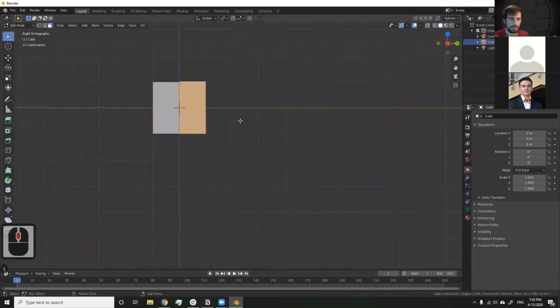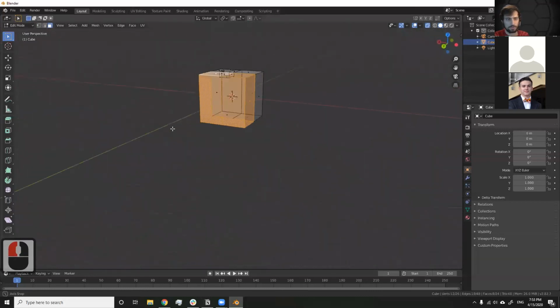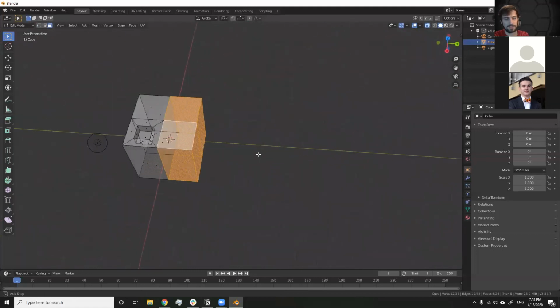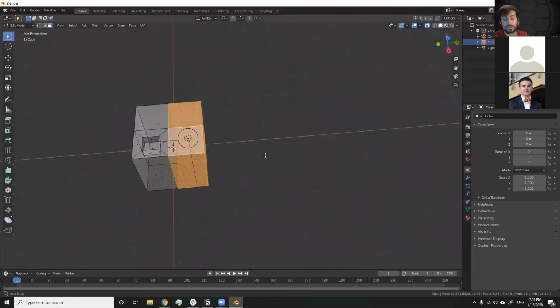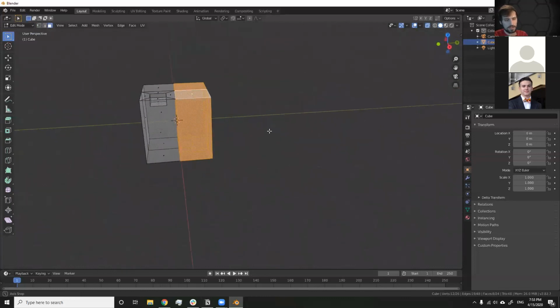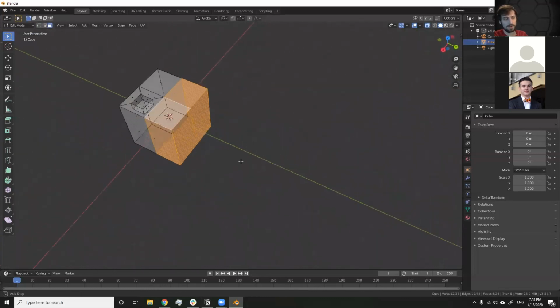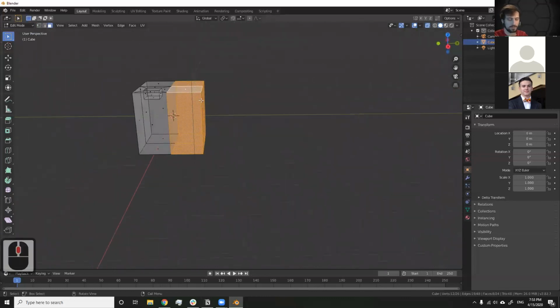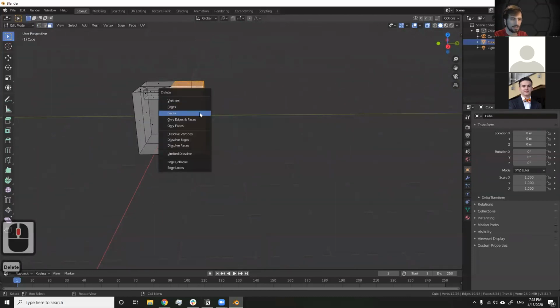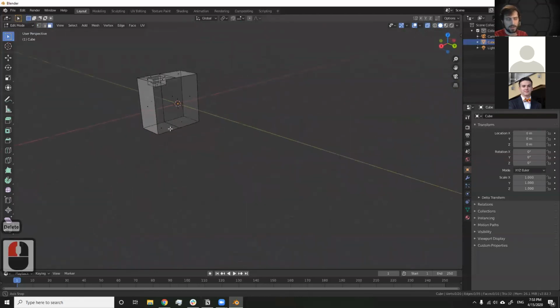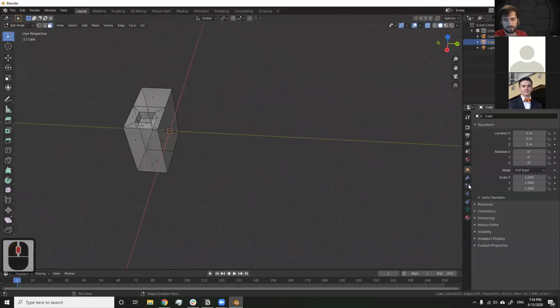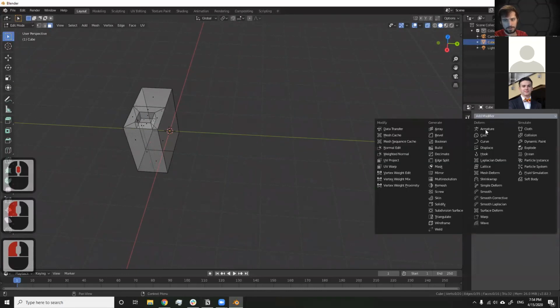But if I go back into here, unselect things, and then hit X-ray mode, if I drag through here now and rotate around, you'll notice it selected everything through the whole model, which can be really, really useful, especially if you want to use a modifier. For example, I can select all of these and hit delete, delete out these faces, and I have half a box. I can add in a modifier and do a mirror modifier.